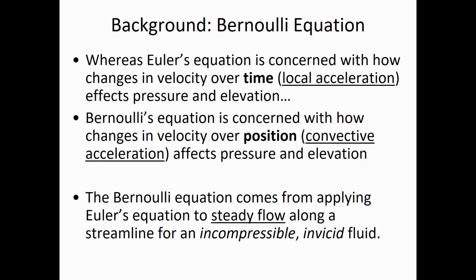A fluid that was inviscid wouldn't experience any friction losses between location 1 and location 2. There would be a pressure change due to the expansion in the pipe, but there wouldn't be any pressure change due to friction or due to energy loss through the friction. So we'll revisit those assumptions, but you need to commit those 4 assumptions to memory. Any questions before we move on?